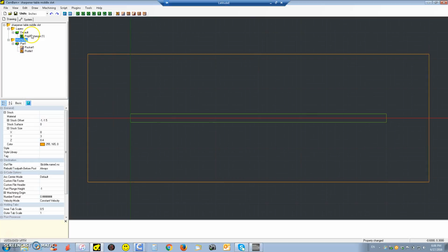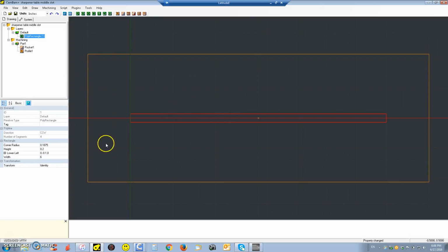So the box that I drew, in red there, is 0.2 inches in height by about 7 inches long, and it's got rounded corners right here. The rounded corners are the width of the bit I'm going to use, which is a 3/16 bit. If I want to have this square, I'd need to use a broach, or it's kind of hard to make something square out of a round bit, no matter what size of bit. I've tried this in the past with a smaller bit, and you might as well live with the little rounded corner right here.